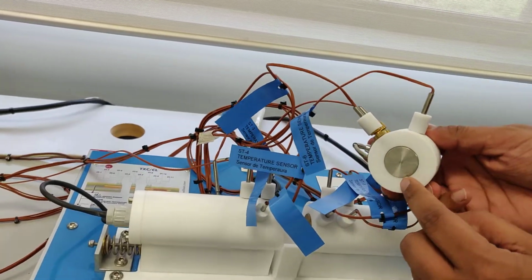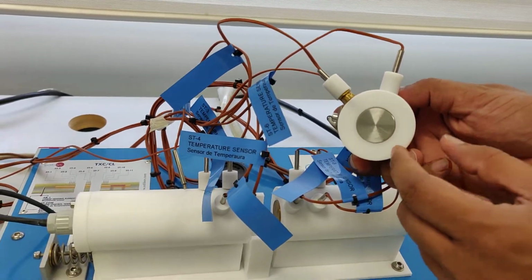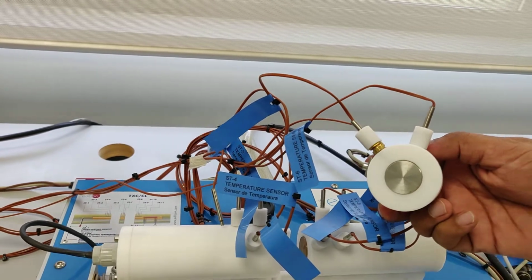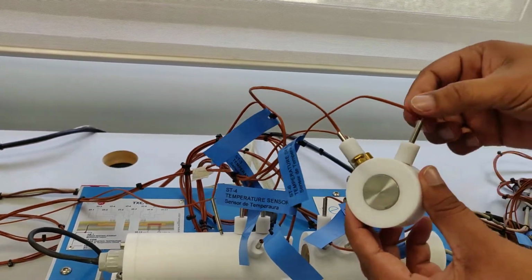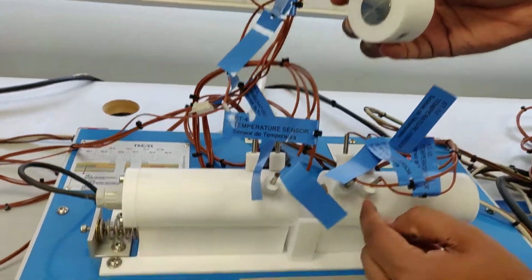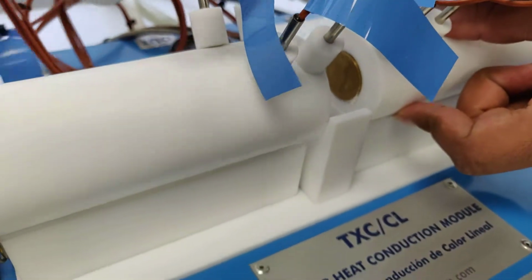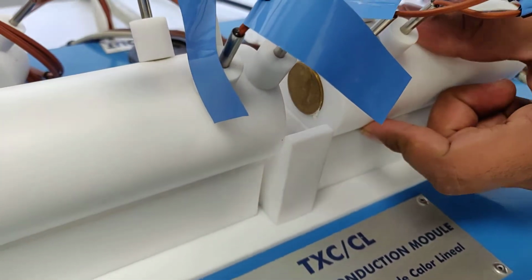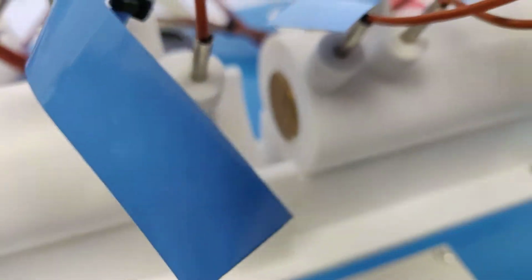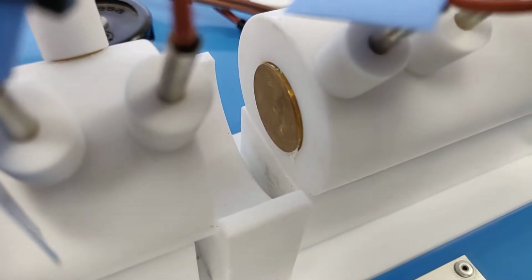So we will know the cross-section area of this specimen, pi d squared by 4. With the diameter measured, you know the cross-section area, pi d squared by 4, and that area goes in our equation for the calculation. Now if you can see the cooling side, there is again insulation, white color, and inside the insulation you have the material, a long cylindrical material. Okay, it is a bronze color.